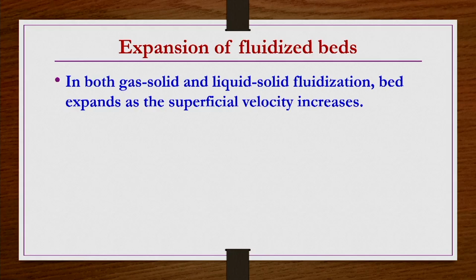So, those things we are going to find out for different types of beds, or different types of fluidization, especially for expanded fluidized beds, and then particulate fluidization, and then bubbling fluidization. For three cases we are going to do this. Expansion of fluidized bed, that we have seen irrespective of the fluidizing medium, whether gas or liquid: for both gas-solid system and liquid-solid system, the bed expands as the superficial velocity increases, once minimum fluidization has occurred.